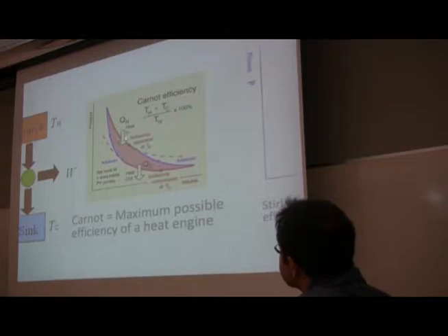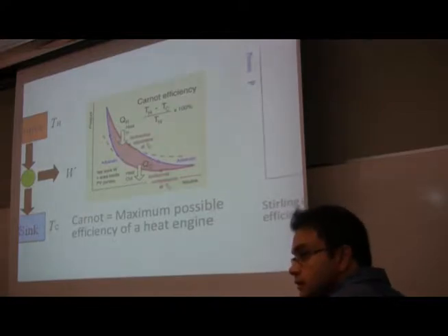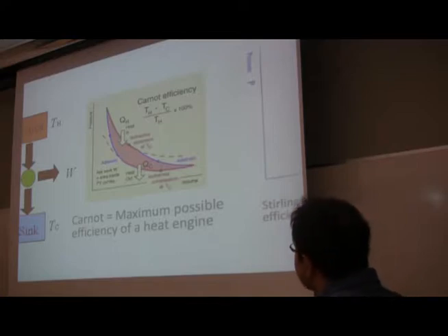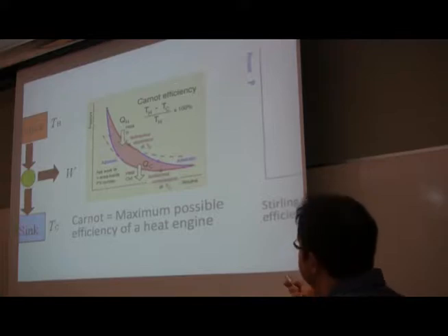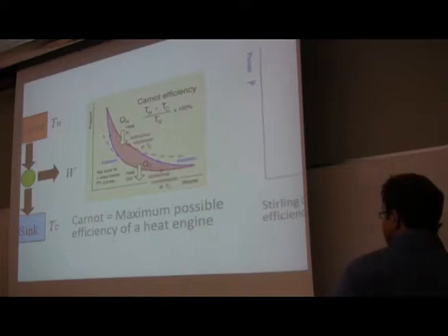Now, during the expansion, you get the heat coming in. So you can think about the fluid expanding. And as it compresses, you'll see the heat coming out. And the difference between those two, the area within this curve, is the work done by the engine. And there's an upper limit to that work done by the engine, determined by this Carnot efficiency. Okay, and that's how that's calculated.